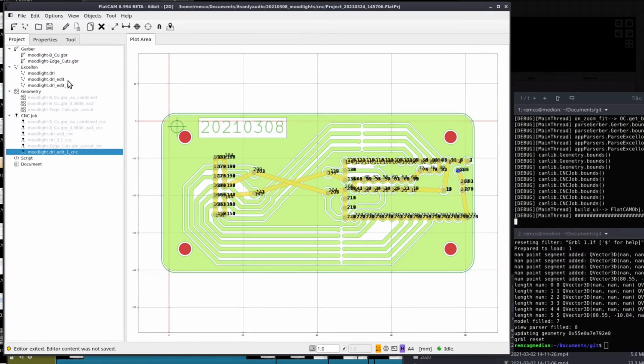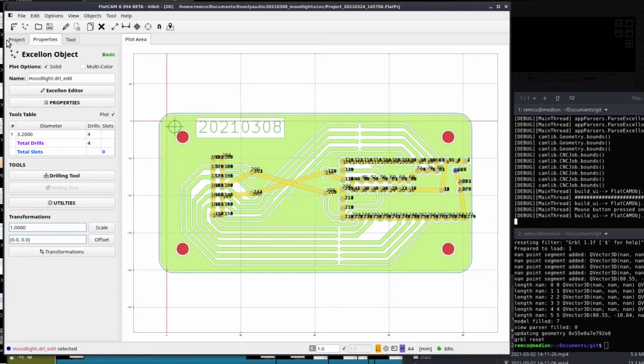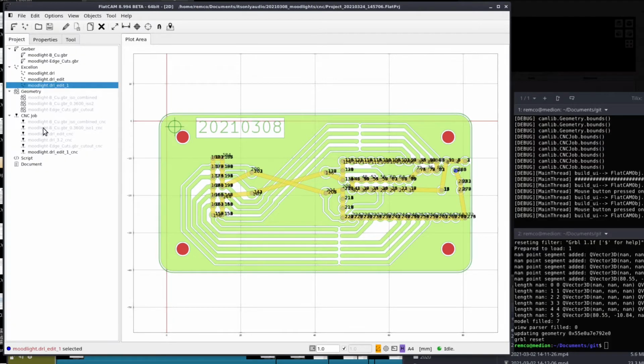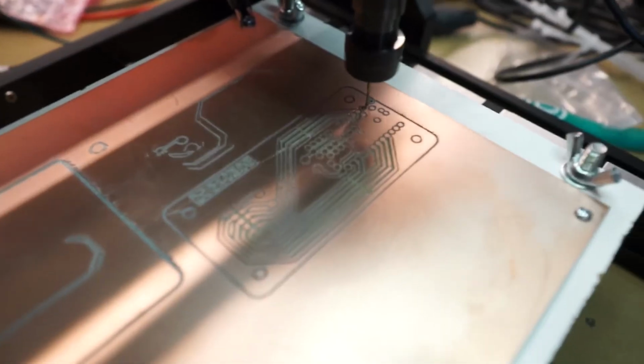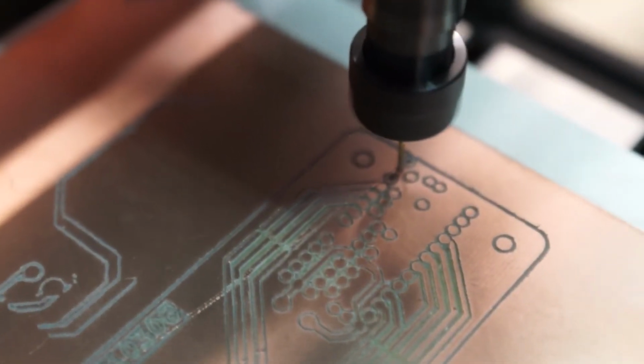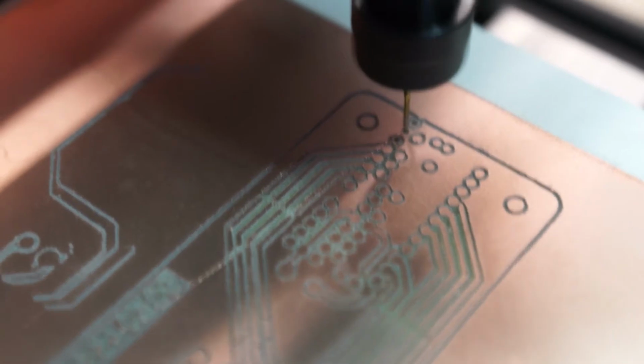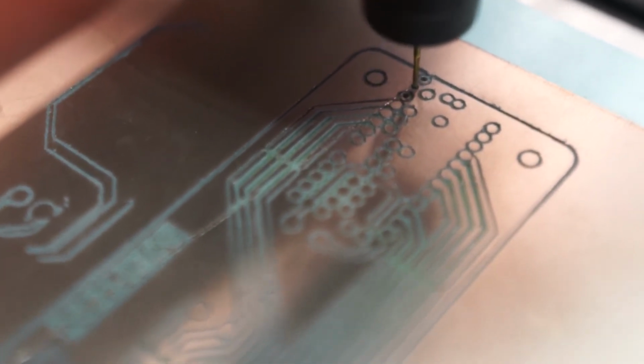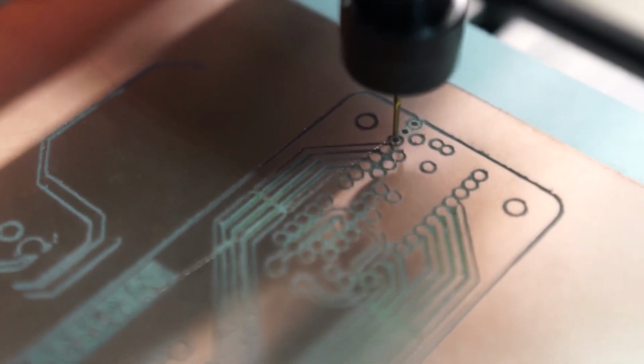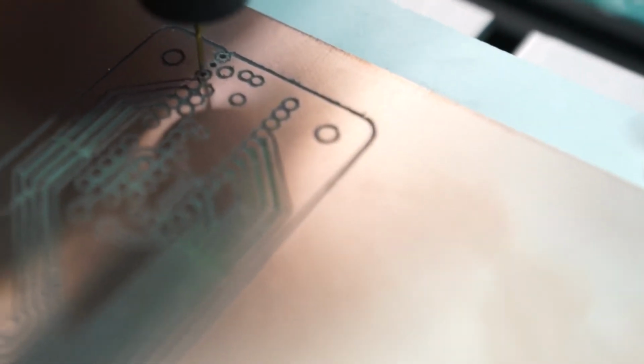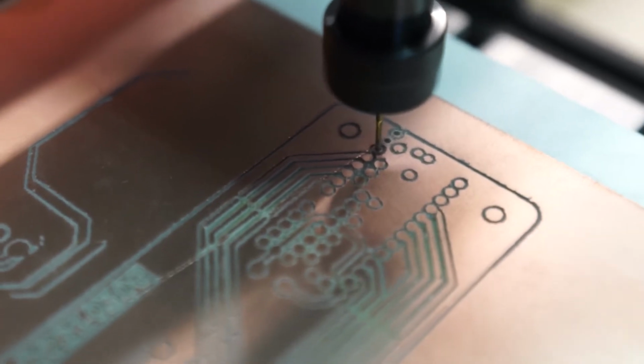So then in the project, you end up with 2 drill files, one for the 3.2 and one for the 1.1. And you end up with 2 drill CNC jobs. And you run them one after another. And that should be good. So it works after I separated out the drill file. You need only 1 tool per drill, and these little mounting holes require a different drill, so I need to make a different CNC file.